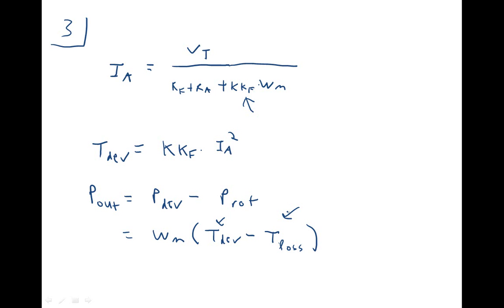So the next one is problem 5 that I got a question on. So in problem 5, a series connected DC motor needs to provide 330 watts. So your output power is known, so you know P out, to a mechanical load. The magnetization curve for the motor is shown. If the input power is given as P in is 430 watts, what is the speed of the motor, torque on the motor, and voltage Vt applied to the motor, assuming negligible rotational losses?